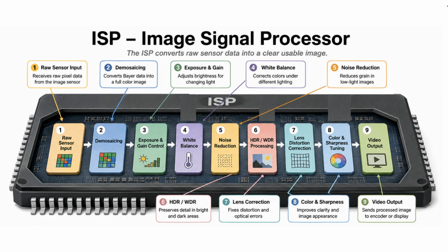So, the complete flow is simple. The lens and sensor capture the scene, the ISP cleans and optimizes the image, and the encoder prepares it for transmission or recording. In a vehicle camera, a well-tuned ISP can significantly improve navigation visibility, operator awareness, and computer vision performance.